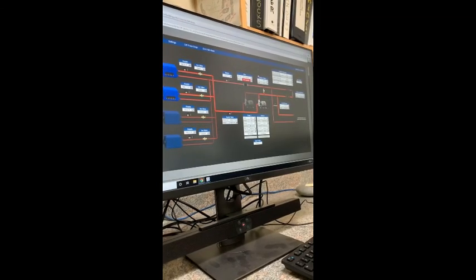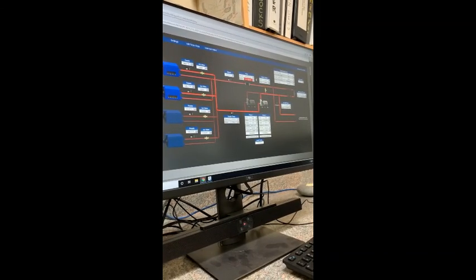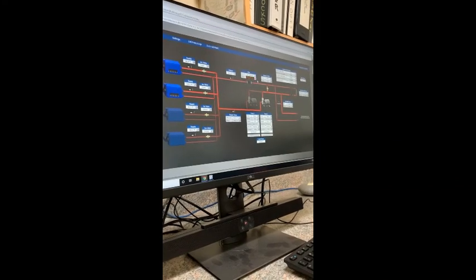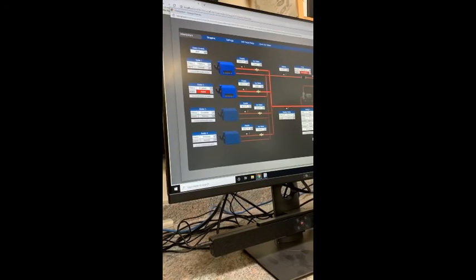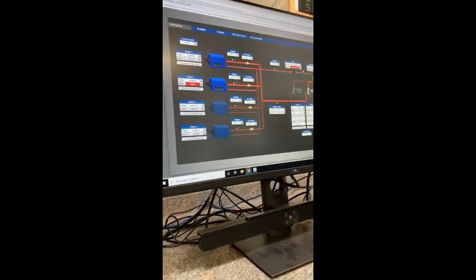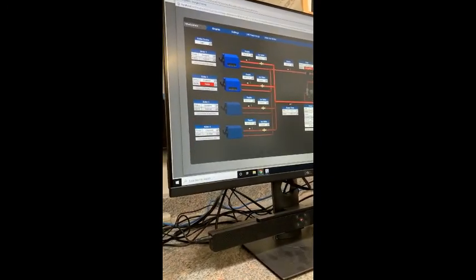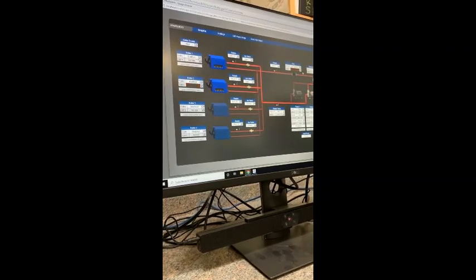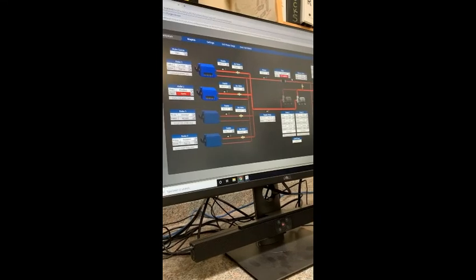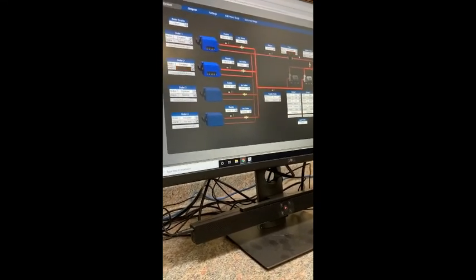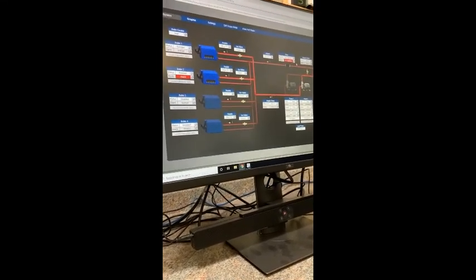And how are we getting flow for that? Is there actually like a flow meter? Yeah, there's a flow meter. It's actually a turbine style flow meter? Yeah. I believe that flow meter is part of the BTU metering for the energy of it as well. So it's that flow meter, and it looks at the supply and return temperature and determines how much energy is being used.